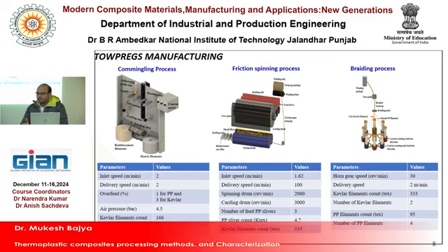So to overcome that viscosity problem, because with higher viscosity the polymer will not be able to flow during the composite formation, we are mixing the matrix at the filament level. Then you will get an appropriate, uniform, void free composite. That is the target of using this commingling process. So nowadays the commingling process is more popular for preparing thermoplastic composites.